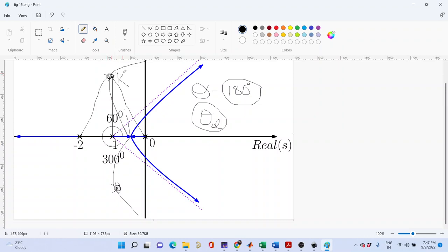Once you find the value of k, you add a controller k divided by s minus p1, or s plus p1, whatever it is that you want to add as a controller. So you add that as your controller, and then you have designed the controller. This is how design is actually done. Things that you have studied are just tools, but there is hardly any course which teaches you how to use them. Maybe you would learn that in your master's or postgraduate course, but this is the main logic why root locus is important to us.